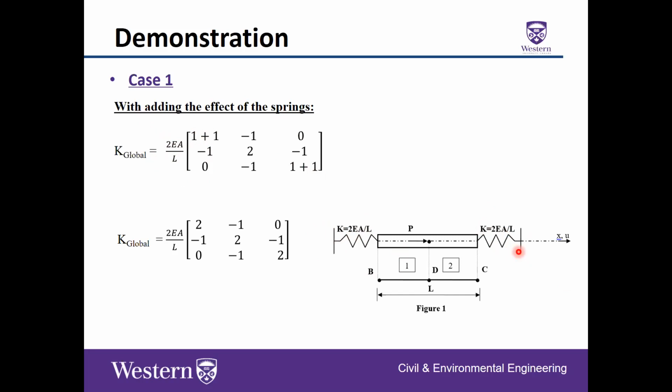We can do the same thing, but sometimes we do it with numbers, so you have to be attentive to the numbers as well. For example, if you formulate the global stiffness matrix after you formulated the local stiffness matrix, and the constant here is like 500, and then I give you the spring constant as 100, you have to see these small details. 500 equals 5 multiplied by 100, so you can just add 5 and take the 100 outside. So that's what I meant.